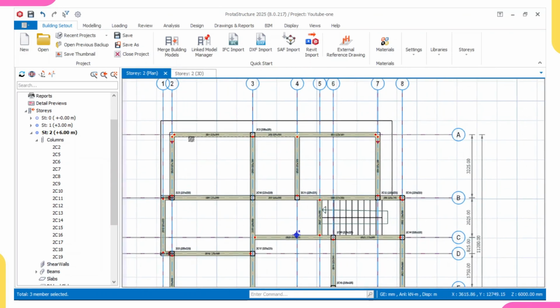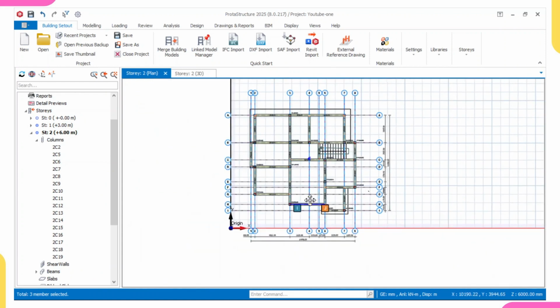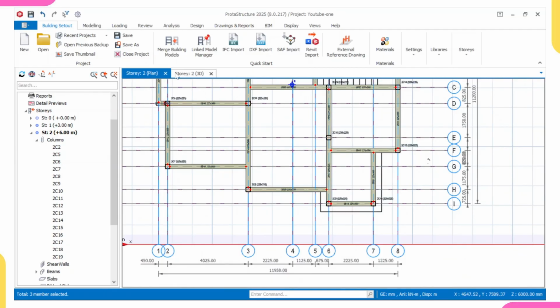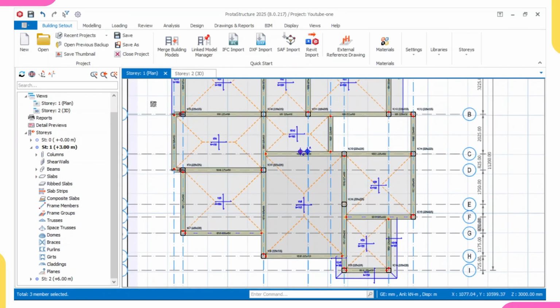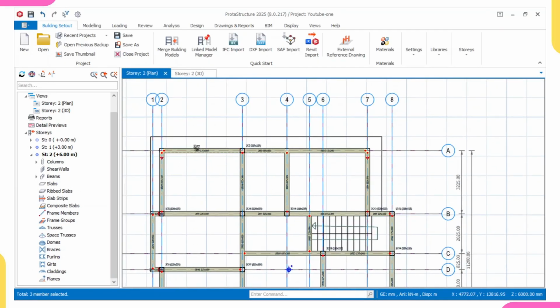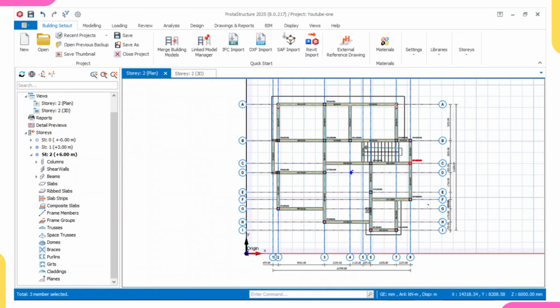Okay, yes, now it's appearing in this second story, because if you can see now, this is our cantilever line. As maybe you can remember, we have not seen this cantilever line before, and also look at this our cantilever line. And if you go back to story one, you see it will no longer be there. Okay, it has been covered by this. So right now we are in story two. What we will do now to model, because we have to move this beam to this point, this beam to this point, this beam to this point, all these beams to this point, even this.